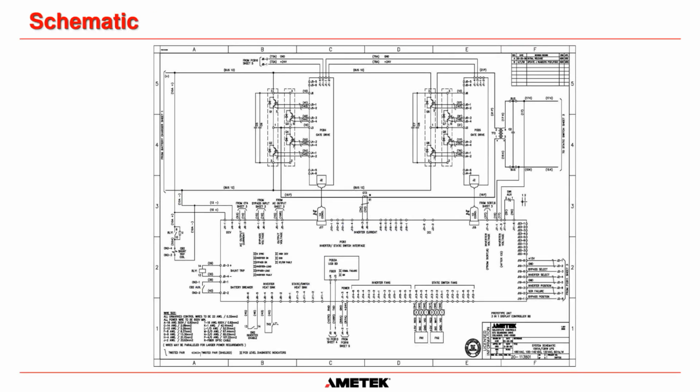And here is the inverter bridge, drawn as it would be in one of our diagrams. As you can see, this would be classed as Q1, this would be classed as Q2, this would be classed as Q3, and this would be classed as Q4. Now, bear in mind, there are two IGBTs. We can parallel IGBTs to get more power, but you can just think of it as one IGBT.